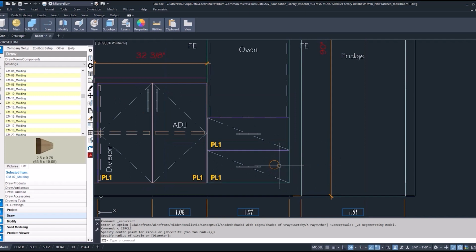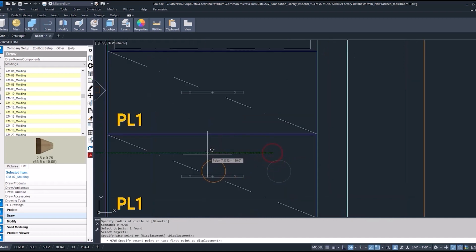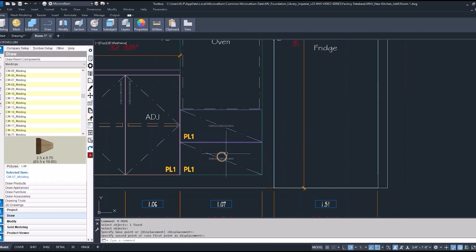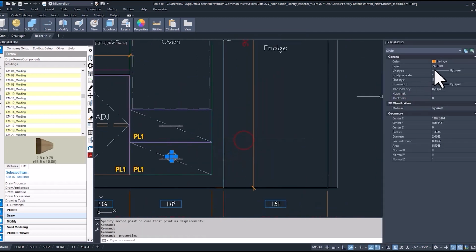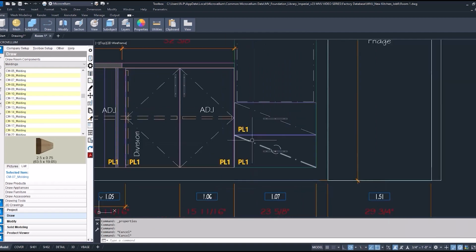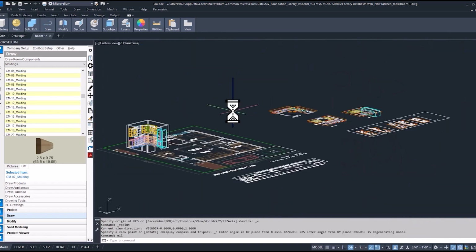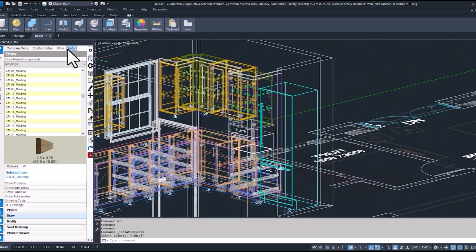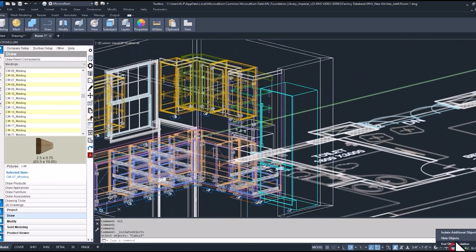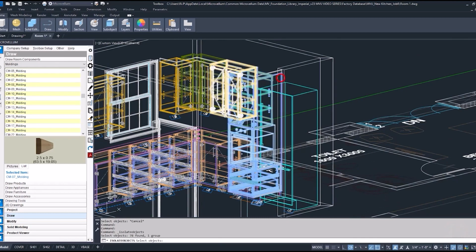We want to make sure that we have a cutout in the side of our cabinet and then also go into the drawer box and decrease the depth on that. So depending where this cutout is, if it was in the center or something, say like that, change my line type to a dashed. So that's what we're working with. We can now go back into our tall cabinet and make some modifications. Make sure we have our select entire product on, isolate that tall cabinet.